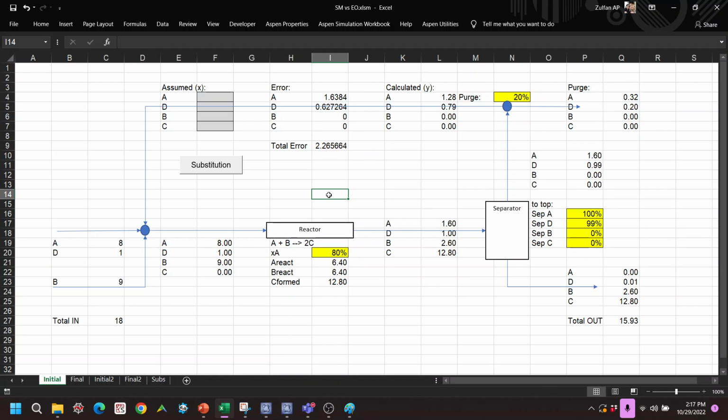Okay. So that sequential model, how does it do that? It will then see the error between them, and then it will then just simply substitute. And I have like this successive substitution. So we can go to the book of Turton. So they will then explain to you what this successive substitution is. So it's like a lower version or easier version of Wegstein, but it's more advanced. I mean, slightly more advanced than simply direct substitution.